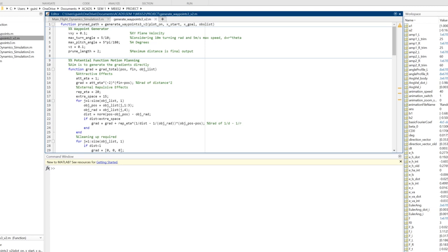I will be explaining the motion planning algorithm we wrote for our system. Since our flapping bird is quite light and it cannot use onboard sensors or the usual motion tracking systems, we have considered using an ultra-wideband tag or UWB tag as the object. This can emit spherical wavefronts that can be detected by our flapping bird, and think of it as a spherical obstacle, which is what we used in the simulation.